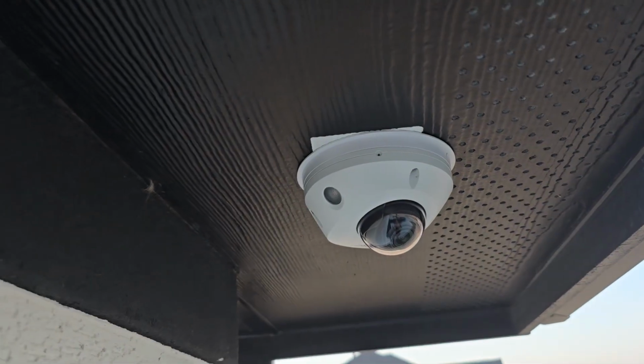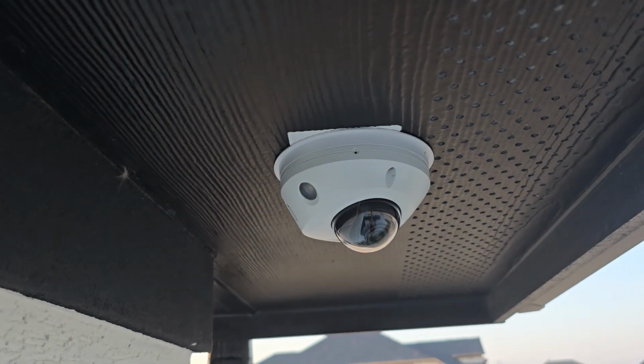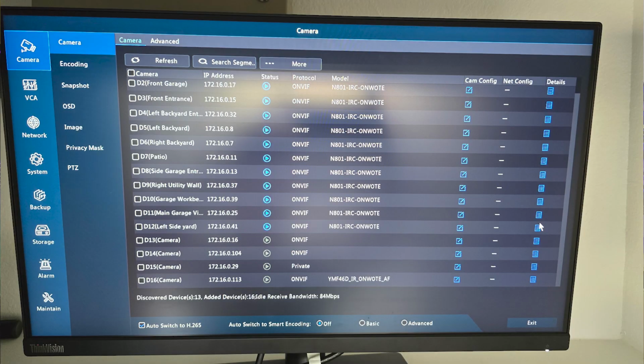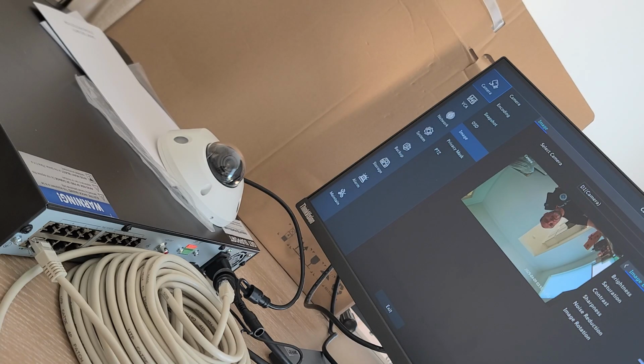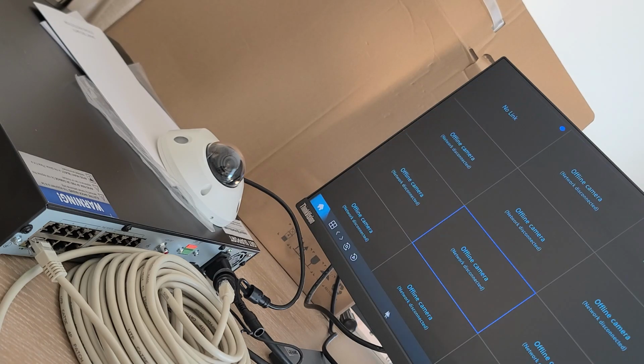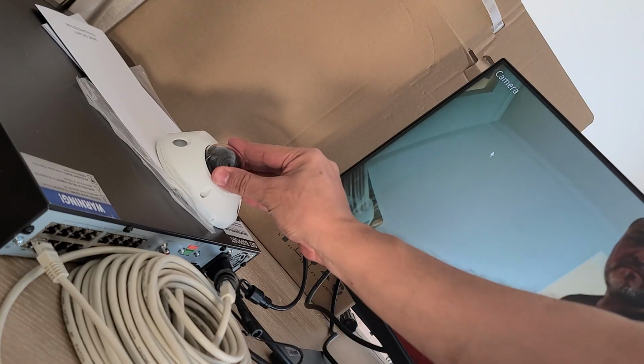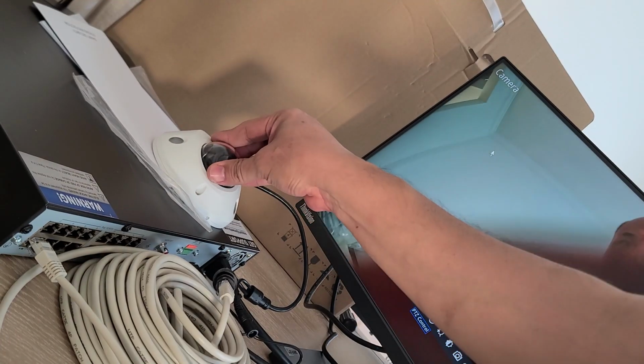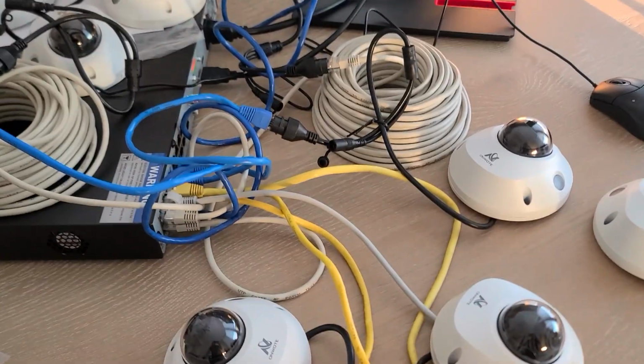Remember that they come pre-installed for ceiling mount. We can still rotate the image from the software in the NVR. In each of the camera's menus, it will show us the IP address assigned by its switch and the camera model. This is also where we can set the username and the password once we're finished. Here's an example of rotating the image received from the camera and the people detecting feature in action, which is very useful as we'll see in chapter 4. We'll follow the same process for the rest of the cameras we're going to install.